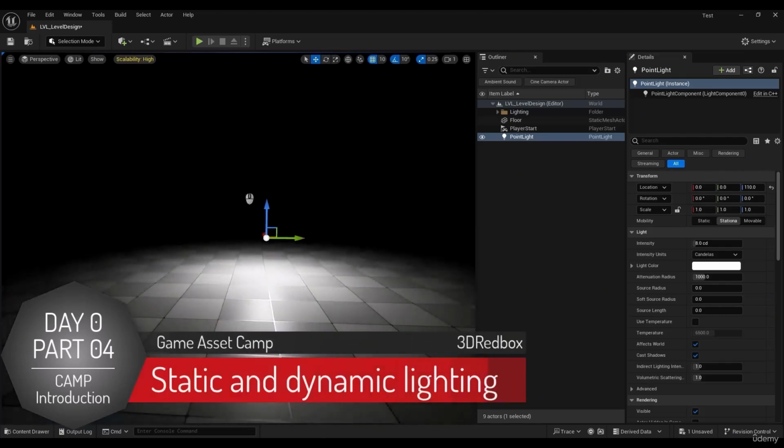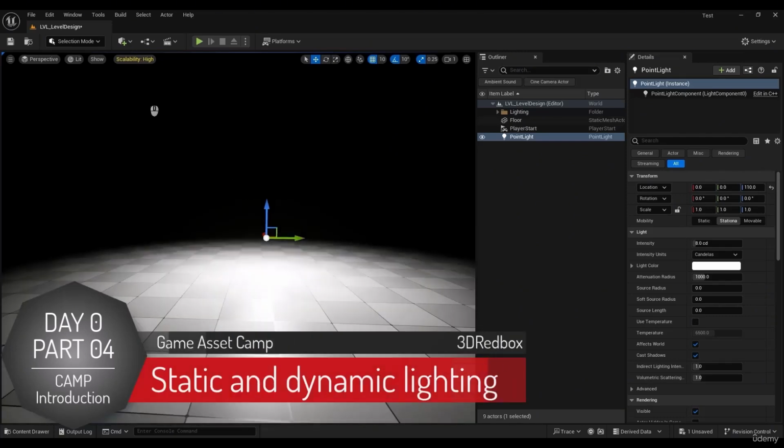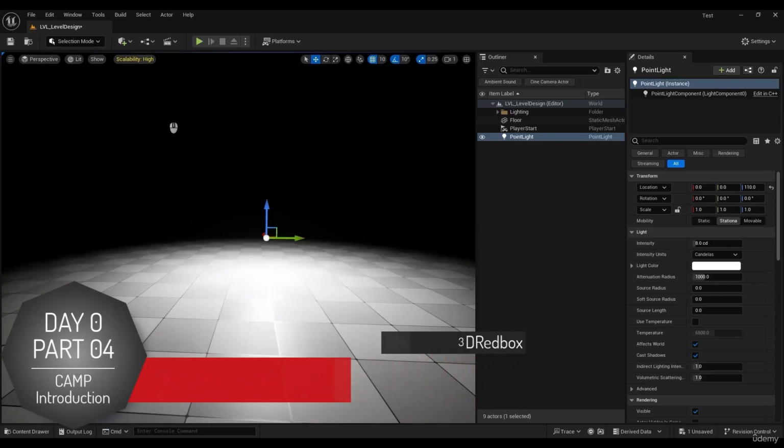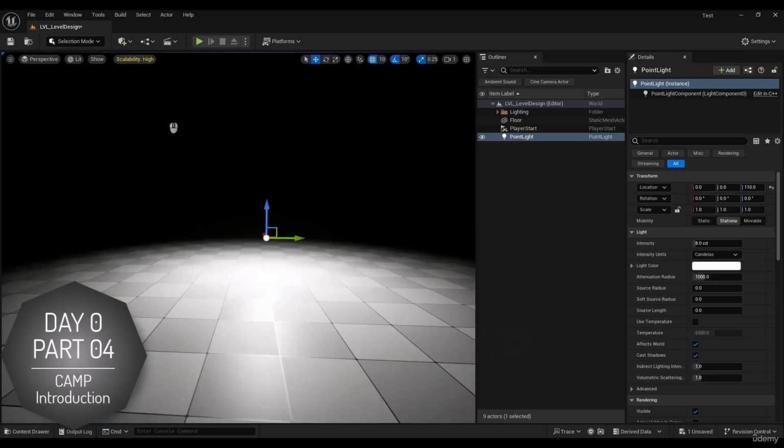Well, we see that light exists in the scene. It is being calculated. Let me tell you an important point here. The first item is about game engine lighting systems. Generally, we have two lighting systems. One is static mode, meaning all your lighting conditions are saved, stored, or as they say, baked. And then the speed, or that FPS, soars to the sky. Why? Because no light calculation happens in real time anymore.